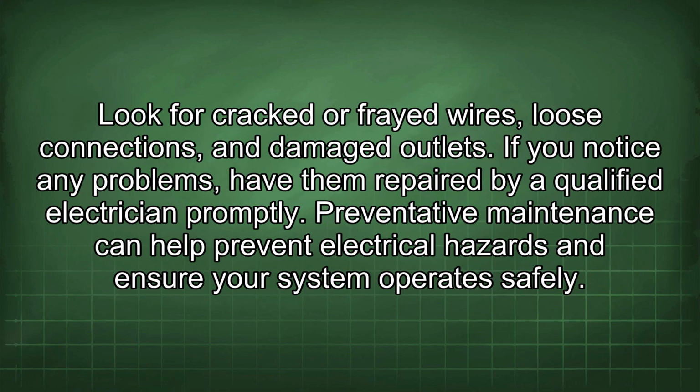Look for cracked or frayed wires, loose connections, and damaged outlets. If you notice any problems, have them repaired by a qualified electrician promptly. Preventative maintenance can help prevent electrical hazards and ensure your system operates safely.